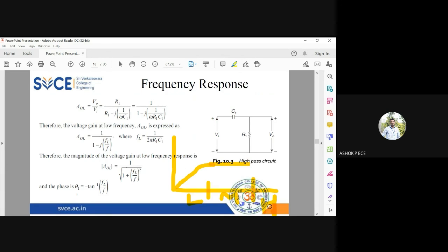In the high frequency region, it is going to act like a low pass filter. It is going to block all the high frequencies. So the graph will be slowly coming down like this. So the amplifier response graph will be increasing, constant, decreasing. The constant portion is mid frequency, the increasing portion is low frequency, and the decreasing portion is going to be high frequency. That is what you have to understand from the frequency response graph.